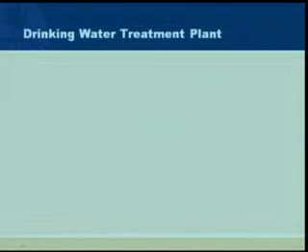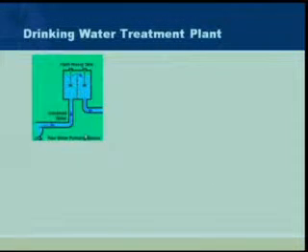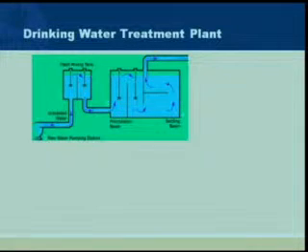And we take this source water and we add chemicals to it. So the raw water comes into a treatment plant. We're talking hundreds of millions of gallons. We add chemicals to it called alum. And this alum forms a gelatinous mass. And this gelatinous mass gets bigger and bigger in these flocculation basins, and then it slowly settles out. As the alum settles out, it actually traps the particles in there. And this is part of the treatment process.